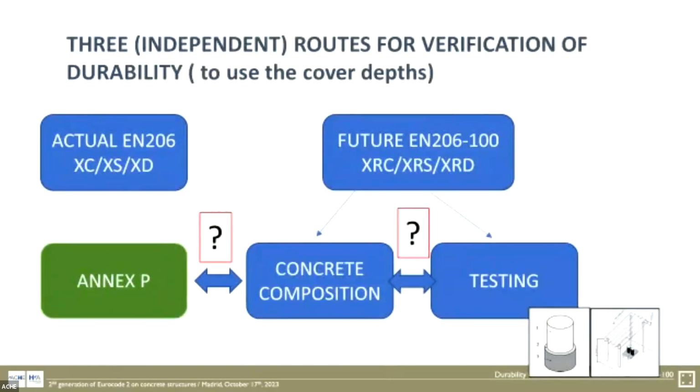Well, how to fulfill or how to comply with this new concept? There will be the mix proportioning and of course the crack width and so on, but for the type of concrete, it is EN 206, and with the exposure classes you have the mix proportioning. And this is summarized in Annex P now. And this will be allowed during some transitory period, not yet defined.